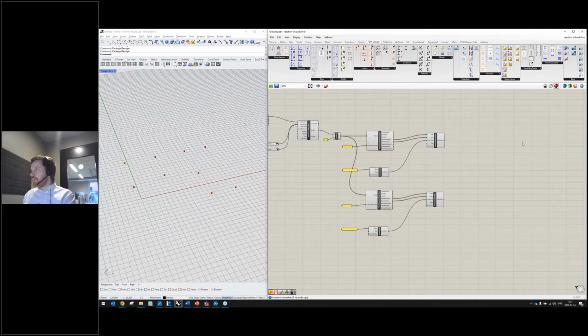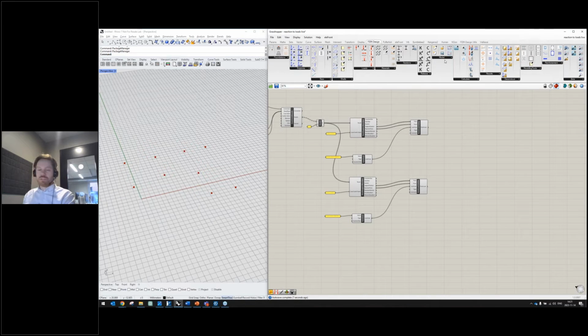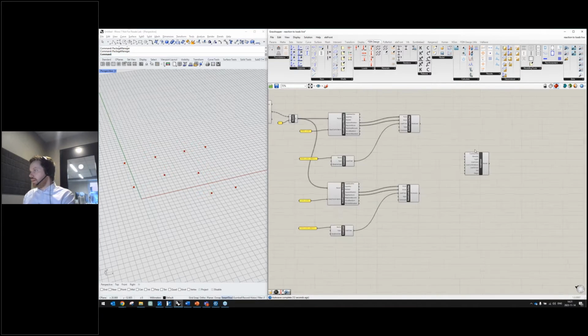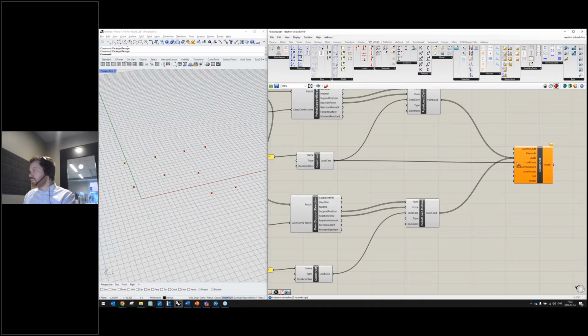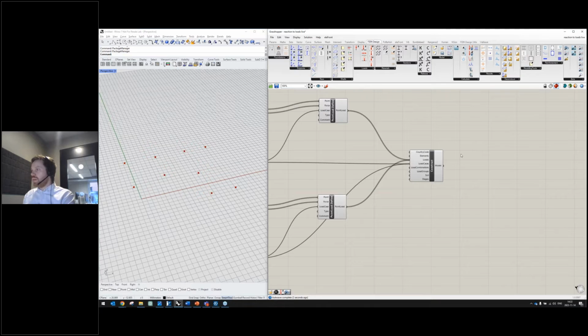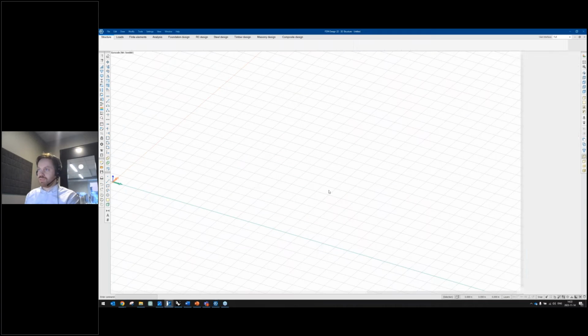Okay, let's take a look at the model. I can construct a new model by going to model construct. I can add different elements. So let's add the point loads to the loads input over here as well, and also the load cases to the model like that. And now that I have the model, I can open it in a new window. So let's go to model, open, and I can just feed it into here, and it will open this new model, which contains my new point loads that I just created from the reactions from my previous model.